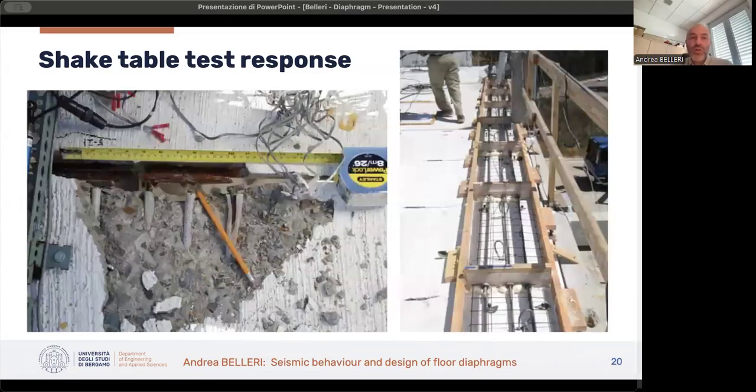So the floor that was damaged was repaired, and a new core system was provided and was made by traditional reinforcing bars with friction welded at the ends at steel discs, and then these elements were welded together.